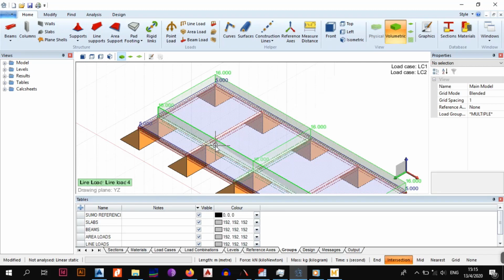And the reason also why I picked 5 is because if you really look at the BS, it says 4 for places that are susceptible to crowding, but then I went with 5 because this will also cater for, if you see when we were designing all of our beams as well, we were saying 25% of the live load will remain permanent, so that will also cater for the finishes and everything. So 5 is already sort of an overkill for the slab, so 5 will cater for the finishes. Don't worry about it. So 5 and the self weight is okay.